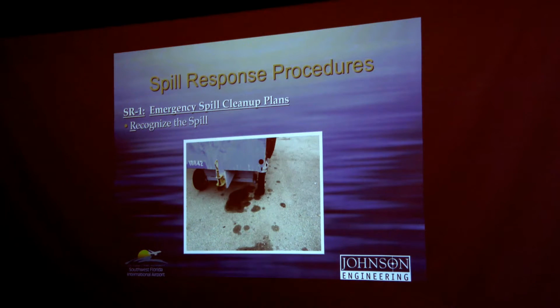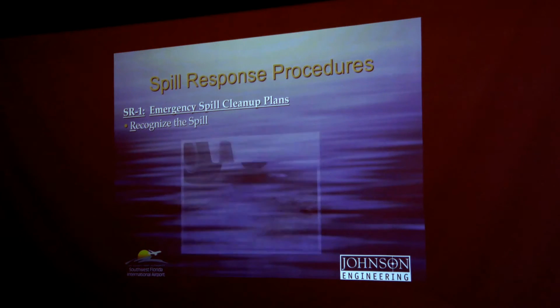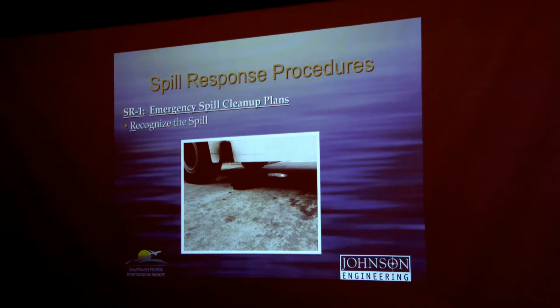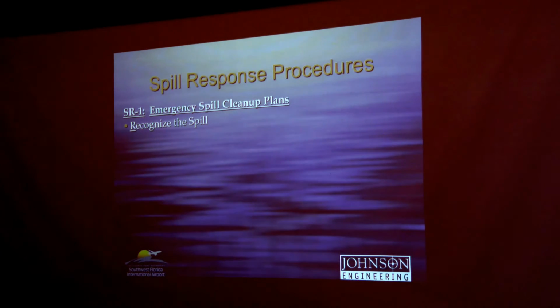A lot of times equipment will have little leaks, little drips. This is out on the tarmac next to a luggage cart. And a lot of times pieces of equipment have little leaks. None of us run 100% all of the time. So when you do see these leaks, take note of them and actually do something about it so that they don't become worse. If you can do it safely, evaluate the spill volume. Make sure it's not still spilling. How much more might be spilled? And can it reach a storm drain or an unpaved area?